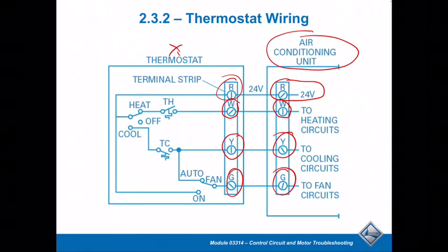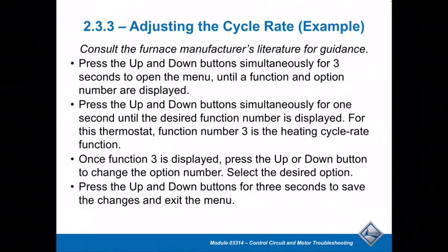On some thermostats, they may have multiple designations, and depending on how you program it will determine how it works and which terminals to wire to. So you have to look at that a little bit. Like I said, that's typically on the sub base of the board. All right, cycle rate. Earlier I chatted a little bit about something called an anticipator. We try to get away from anticipators, and for good reason. The anticipator is, let's call it, old technology. The cycle rate gives us so much more flexibility in an install.